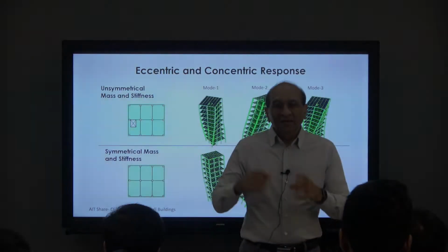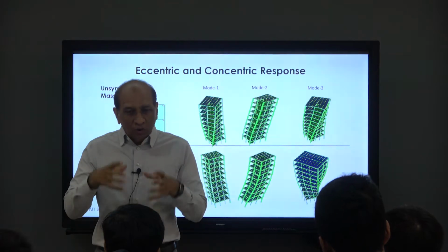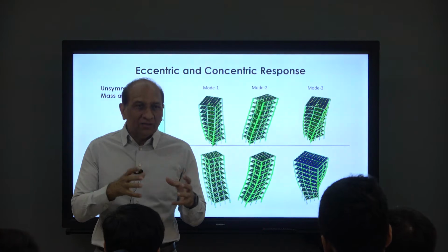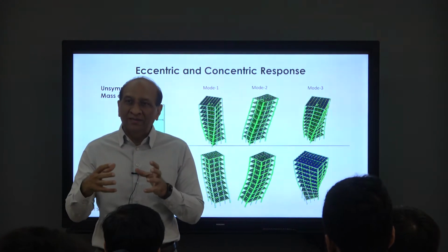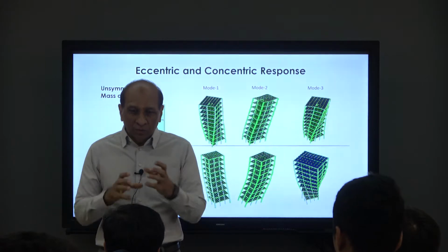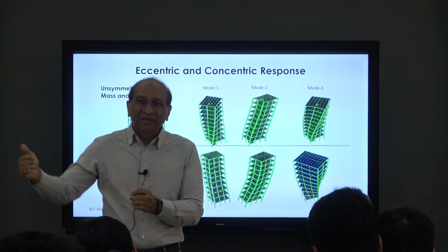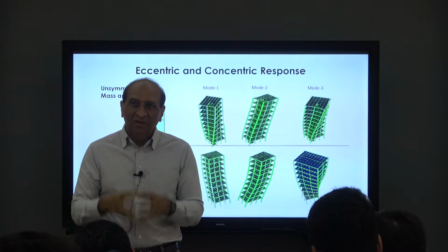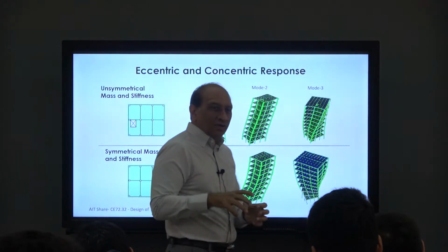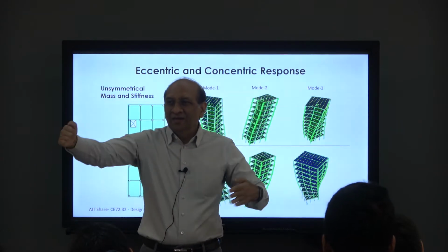stiffness. It is possible, especially if it's a tall building, because if it's a core wall right in the center, completely symmetrical, then in that case the lateral stiffness of the frame is quite large, but torsional stiffness is very small because the core is right in the center. So the columns around that are not providing enough. A flat slab building with a central core will typically have a torsional first mode, because the building starts to rotate about the core, because you do not have end frames stiff enough.